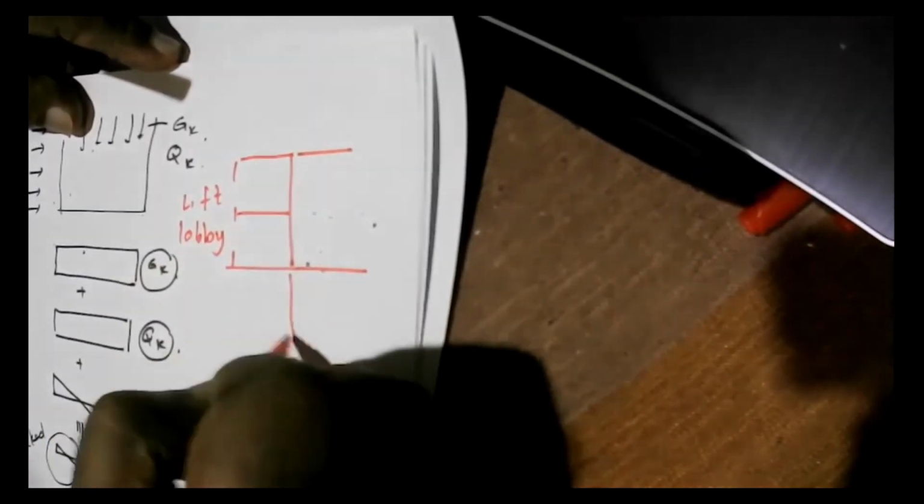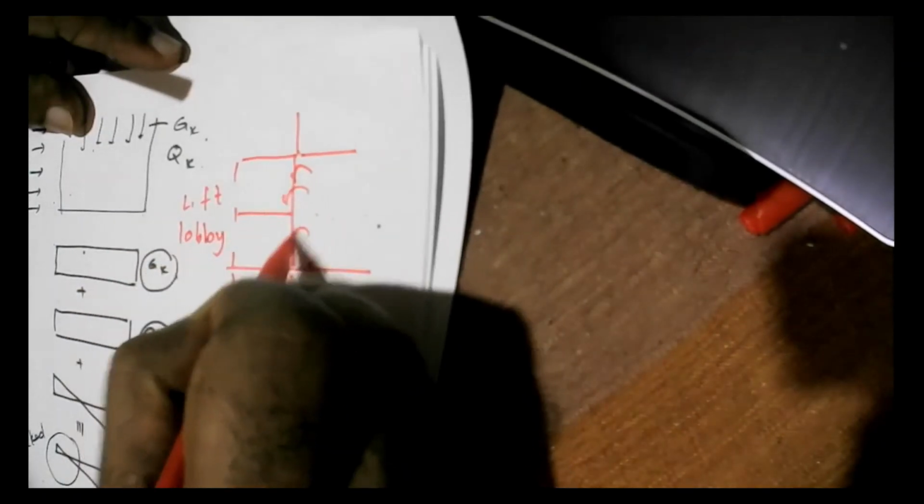So on this side you get other slabs. So if you are having all these other slabs that are transferring the load onto this, and finally to all the main elements, then you will find we can increase the value of Gk, and also we can increase the value of Qk.